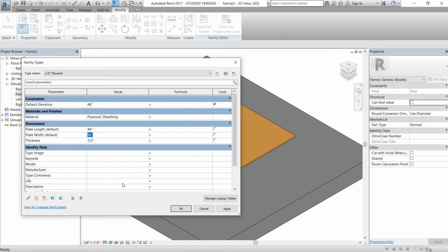So the next thing we need to do is we need to add shared parameters in. The reason we have to do this is so that way when you're trying to reference this to the parts panel when you're doing your scheduling, they need to be referencing the same thing as your studs. So there's a couple items you want to have here, like our part number. I guess part number and cut length would be the 2 main ones that you would want to have.